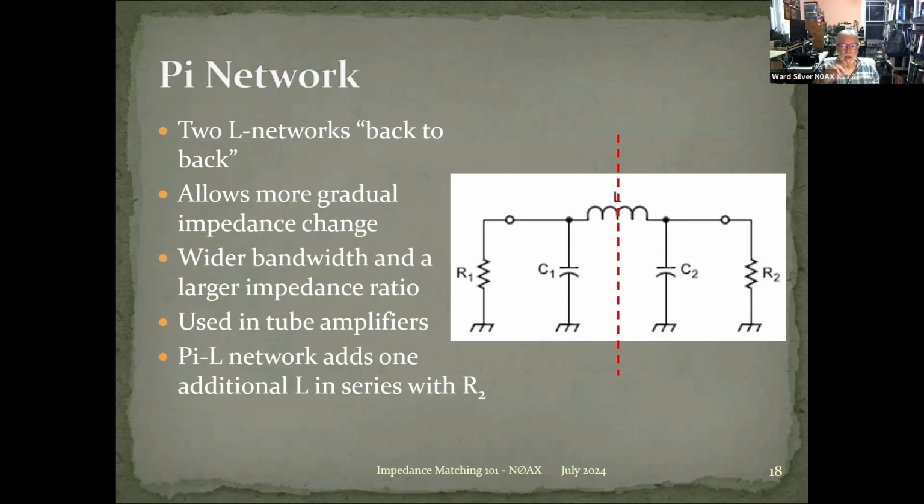Also, the wider apart the two impedances are, the narrower the match is. So to improve the range and what's called the Q, meaning the breadth of that matching network, they invented the pi network. It's like having a little idler gear in between two other gears. It costs another gear, but it allows you to match more impedances over a wider range.